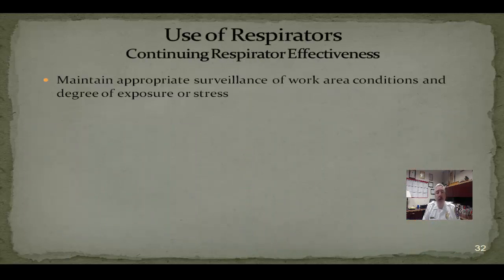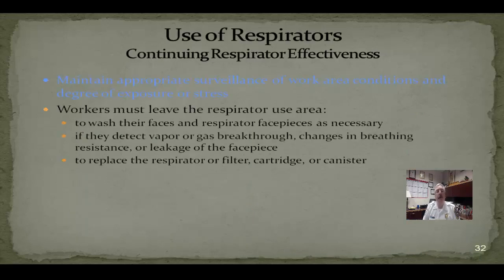We've got to constantly be making sure of the degree of exposure, the surveillance, or the working with the environments we're working in. Workers must leave the respirator use area to wash their face and wash their hands. If they detect vapors or gases, any kind of breakthrough in the seal of the mask, then you should automatically remove yourself from the environment.